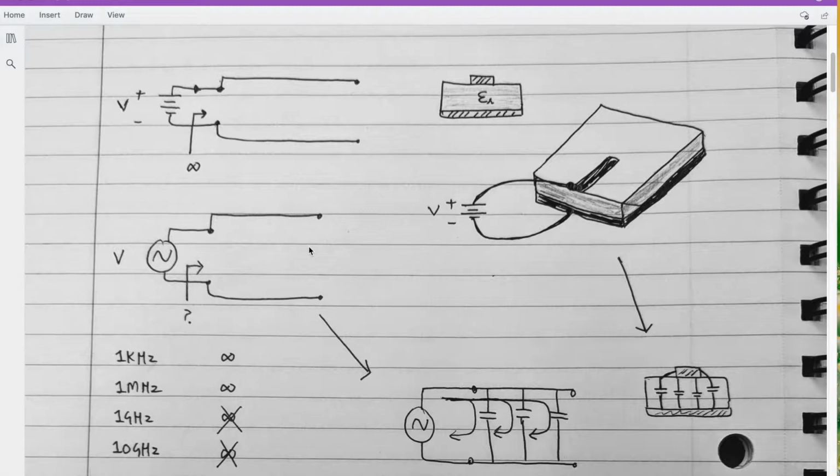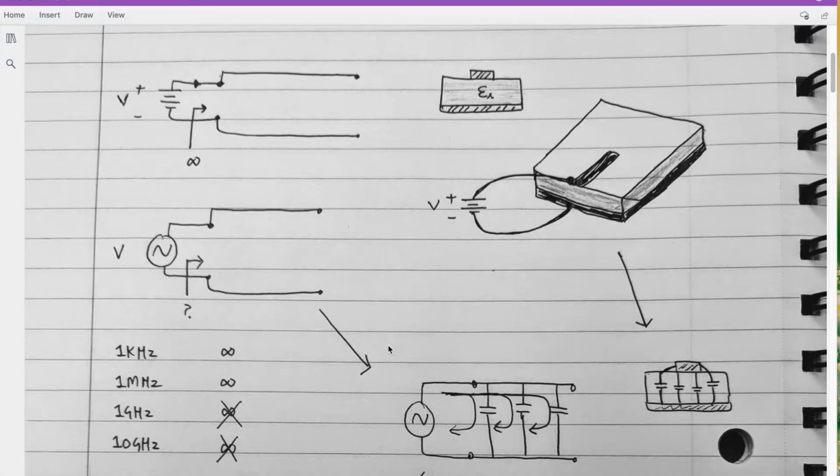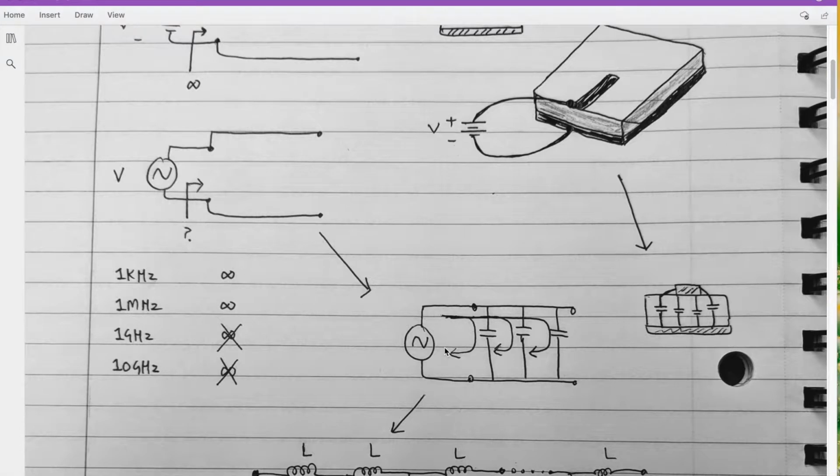Well, visibly yes, but actually there is some current that will flow through these wires, and that current is because of the parasitic capacitance between these two wires. So it turns out at higher frequencies there is some current flow through these wires. That means the higher the frequencies, the more the current should flow, right? So at very high frequency, let's say 1 terahertz, this should effectively short circuit this line because this will have very small reactance, right? So infinite current should flow at very high frequencies.